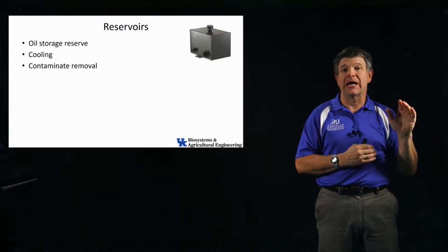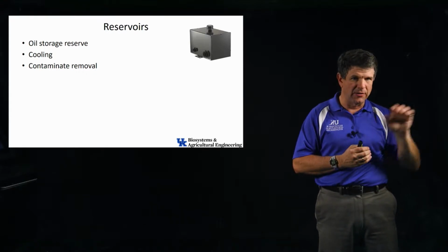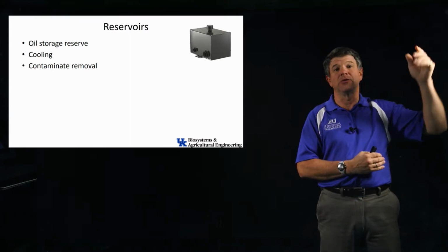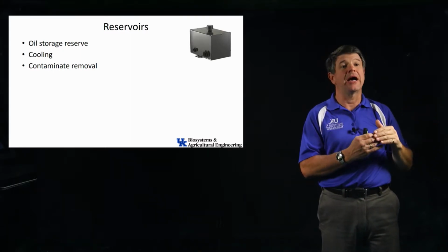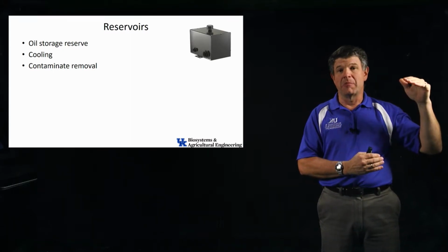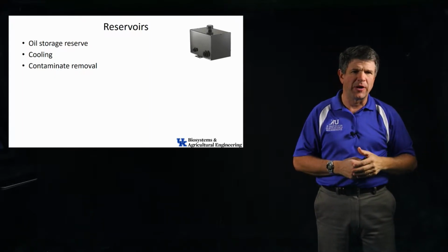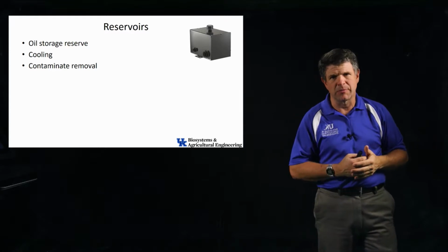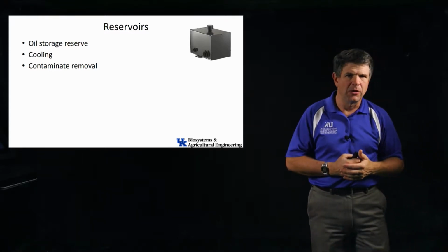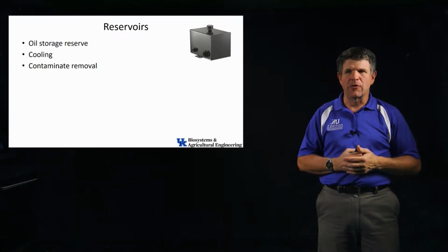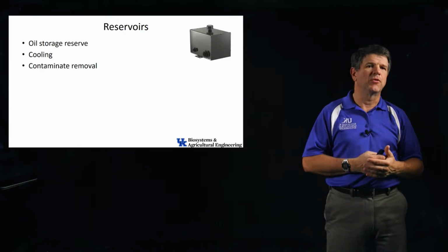Now, if we have single acting cylinders, it's even worse. So I send the fluid out to extend the cylinder, there's no return coming back. I've got to make sure I've got enough in my reservoir that I don't run the reservoir dry. And so that's one of the fundamental considerations of a reservoir, is simply volume and what I could be using.